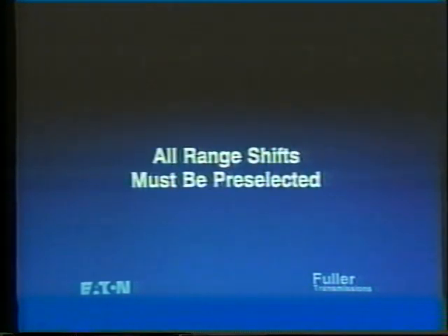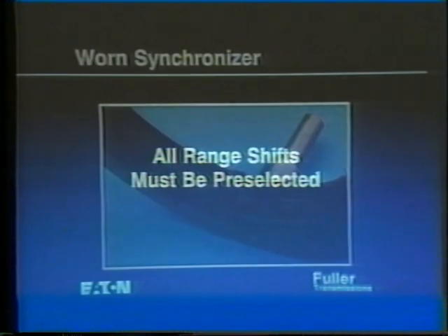Over a period of time, not pre-selecting the range shift can cause damage to the synchronizer and mating parts. This damage results when the driver is not moving the range button until the lever is in the neutral position. All range shifts must be pre-selected.